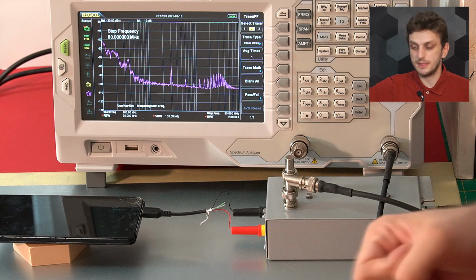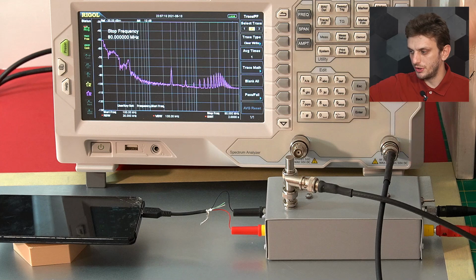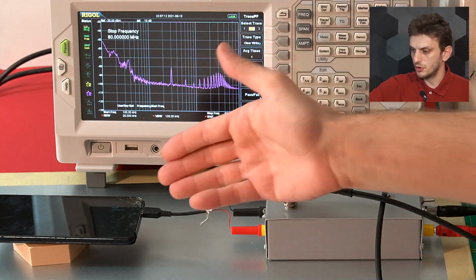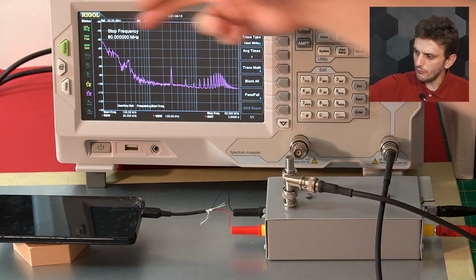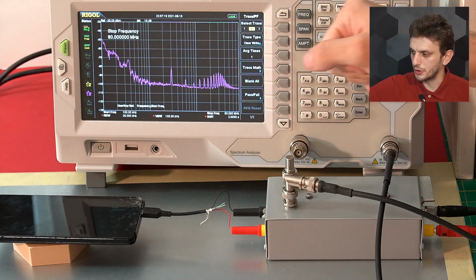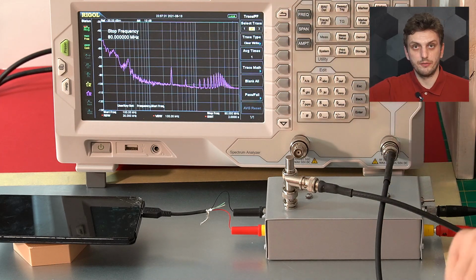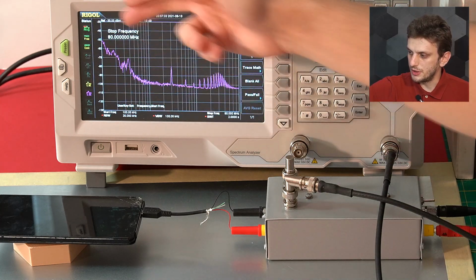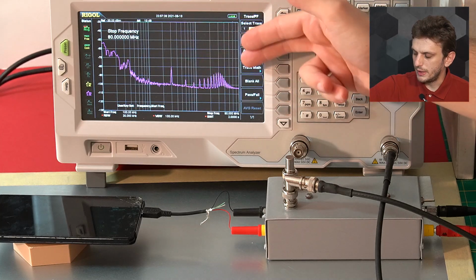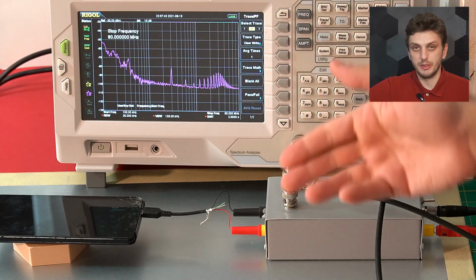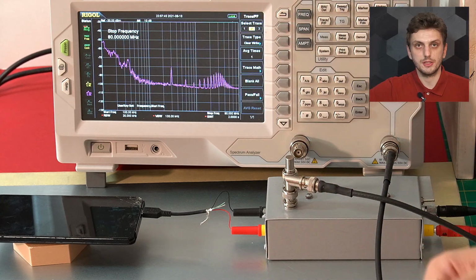So first of all, to get a baseline, I've connected the cell phone through the USB charging port to the LISN, which then goes to a 5-volt supply. So right now the cell phone is charging, it's pulling around 500 milliamps of current, and we can see our noise emission spectrum. So the plot is going from 100 kHz to 80 MHz, so just below the FM band, and we can see quite a lot of noise here below 1 MHz, then we see a clear spike at 3 MHz, and then a bunch of harmonics of this 3 MHz spike. So this is probably some sort of switching converter, and we're seeing its harmonics.